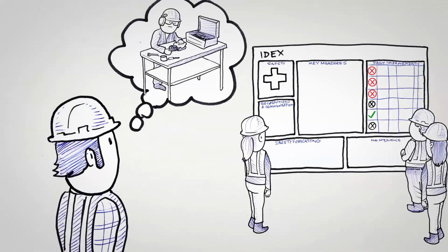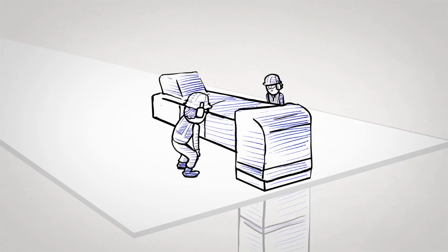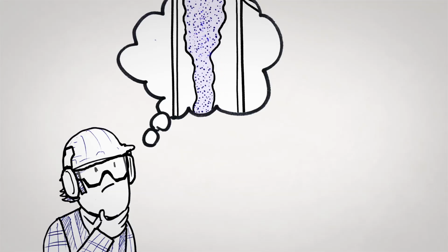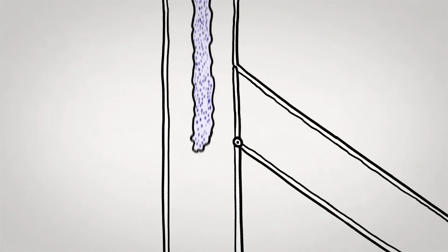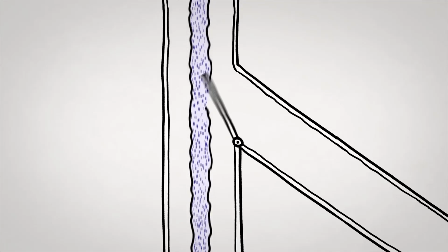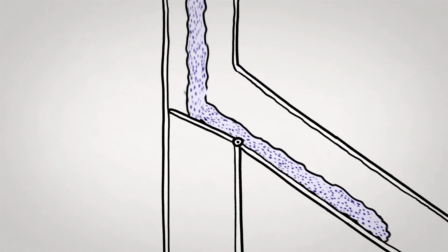Donald figured something additional was wrong, since he knew Igor cleaned the probe. He went out to the plant with Igor and inspected. The level in the discharge spout wasn't high at that moment. He thought, well, maybe we're getting product surges that caused the high-level probe to trigger. While he was out there, he noticed a flap gate downstream of the conveyor and discharge spout. Could our product be backing up when that flapgate changes positions and directs flow to a different conveyor?